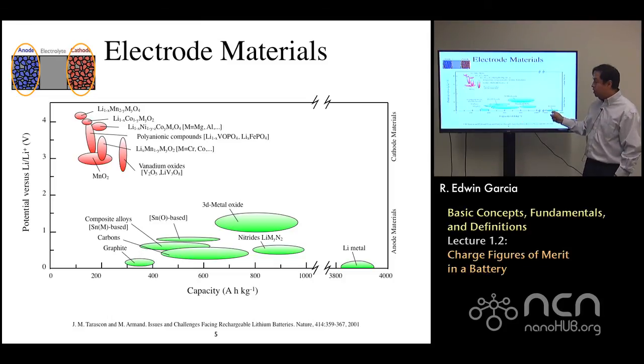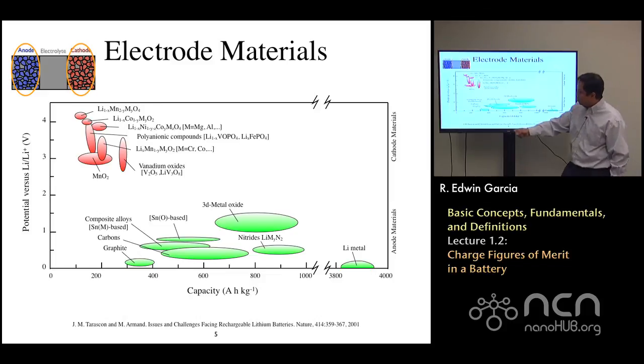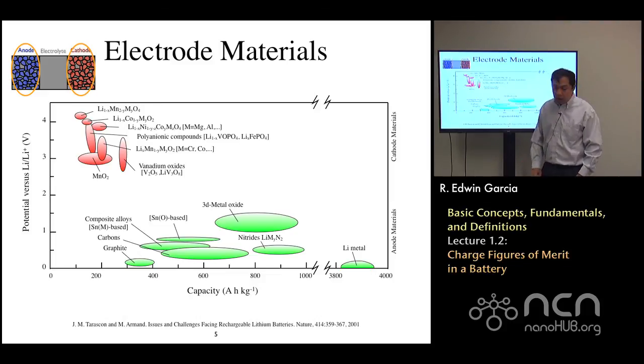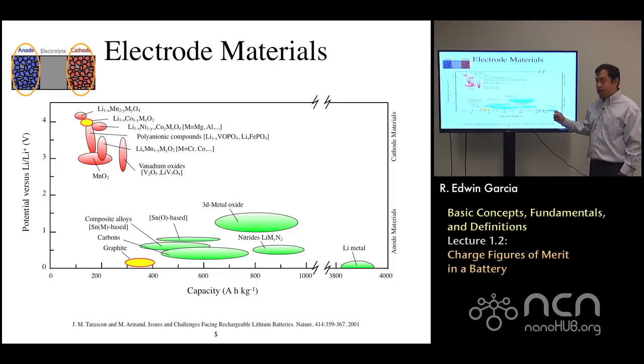Why is it that lithium metal is not being used these days as much as graphite, again, the most widely used material? There are a lot of safety issues that, even after more than 20, 30 years of using rechargeable lithium-ion batteries, have not been resolved with lithium metal. For reasons that will become clear in future lectures, lithium metal develops growths called lithium dendrites that can make the battery unstable, favoring the battery becoming unstable and therefore exploding, or developing, if you're lucky, an internal short circuit.